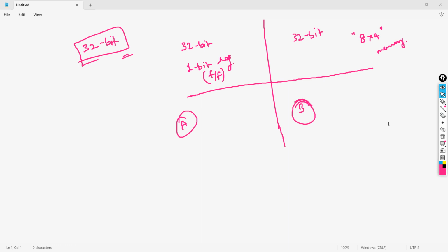These are all things that pretty much in interviews people would ask. You being a designer, now you don't have that memory, but how do you realize that? I would go with this value. But let's say you have an area restriction with respect to your chip. Now I would get rid of individual registers and go for memories, SRAMs. SRAMs are static random access memories where you will store the values.